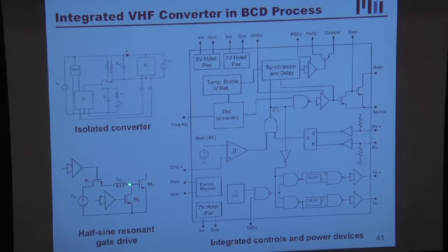What this does is you turn on this transistor, you charge up this inductor, you resonate charge onto the gate of the power device, the charge resonates back off the device, and you recover that gating energy, or a substantial portion of it. And because we have all the integrated devices and controls, we can set up all the detailed control logic to manage that even under startup and all these other conditions that would otherwise be very difficult to do.